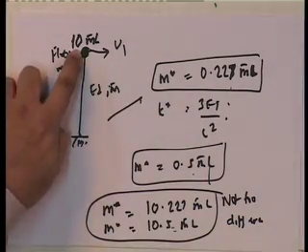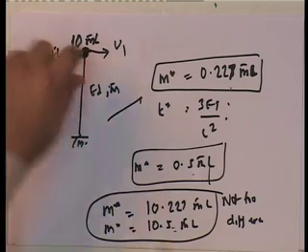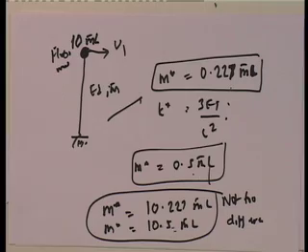And this is the floor mass, because this mass is now very small compared to the floor mass, which is what happens in typical frame buildings. The floor weights that you have are significantly larger than the member weights, always. Which is why in gravity loads, you pretty much always consider the weight that comes from the floors as part of the gravity load. If you look at the reactions and add up all the floor weights, you'll see that that is almost the reaction. So this one doesn't look ridiculous. Therefore, let us be very, very clear that the lumped mass formulation is only valid for framed structures.